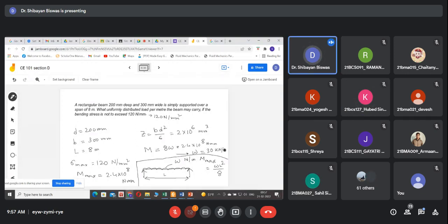Yeah, that is one way of writing. This is easier to write down. Your answer is also correct. No marks will be deducted for those cases, but it will be easier for you to write it in this sort of way. So this is the uniformly distributed load per meter of the beam. So the very first answer which she gave, that 45 Newton. Now you understood where the unit will be very important, and here it will be Newton per meter or kilonewton per meter.